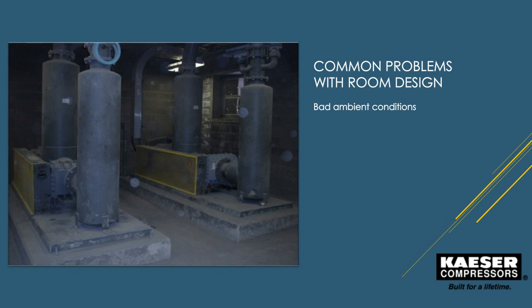The biggest problem that we find with compressor room design is bad environment or bad location. Whether, like we're seeing here, with a dusty, dirty environment, or whether it be in a basement, or location that's ingesting pollen directly into the equipment, or the equipment's underneath sorting equipment where debris is falling on that equipment all the time, moving that equipment to a clean, dry area can certainly help increase system reliability, and in many cases can increase efficiency as well.